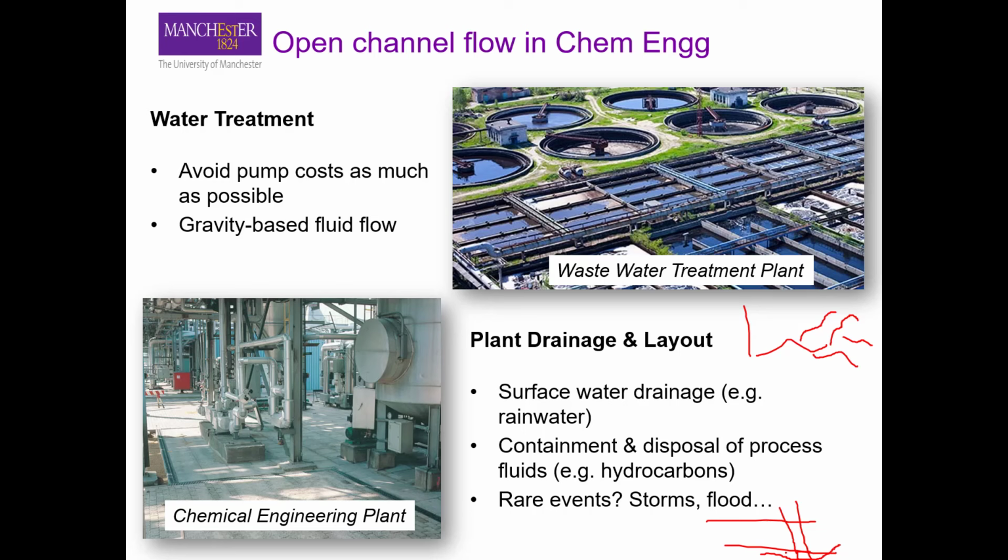Okay, so this soil scour, we need to know as engineers when it is going to happen, and what would be the depth of this scouring around the pier, so that we can predict what will be the effect on the stability of this pier. Okay, so we design our pier depth, or the point where the pier sits on the bed, in a way that the foundation depth, that is this point, is actually larger than this maximum scouring length. Okay, so that again comes under the analysis of open channel flows.